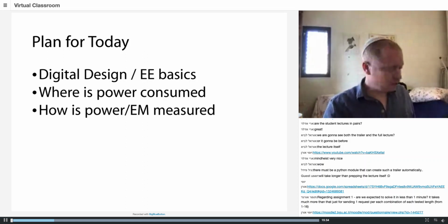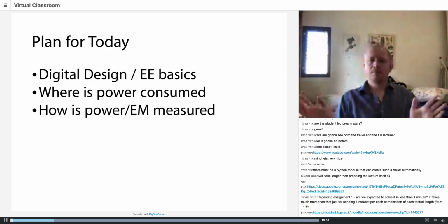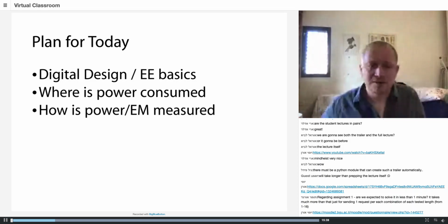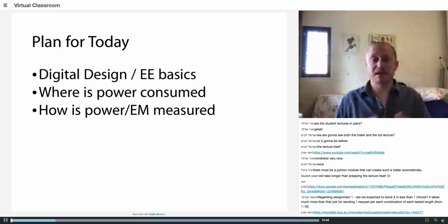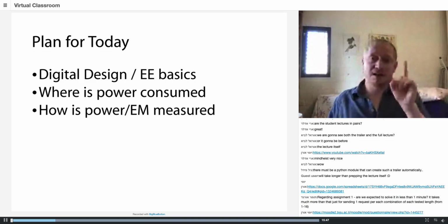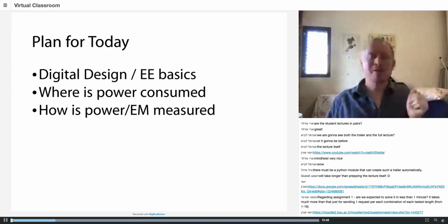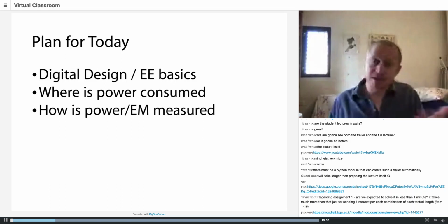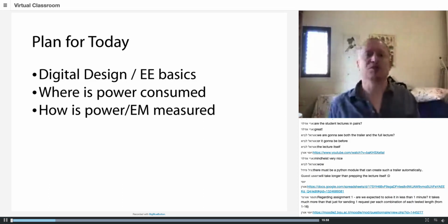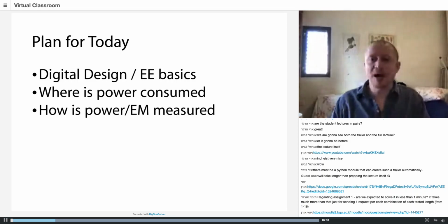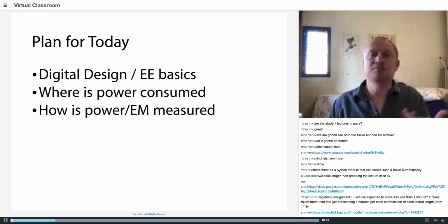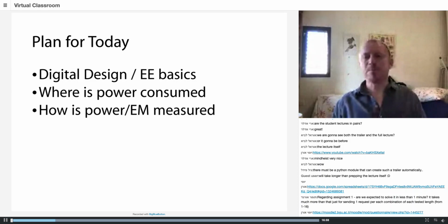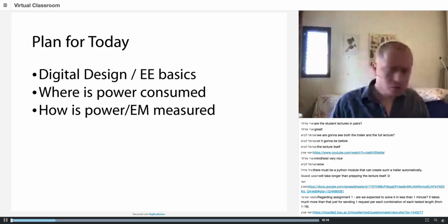So today I'm going to talk about getting you going on the path to performing power analysis. The idea is that previously the attacker had one kind of input, which is the timing, and this got us quite far, but you can do constant time countermeasures. Now we're going to talk about another kind of piece of information that the attacker can have, and this is the power consumption. So I'm going to talk about why devices consume power, how they consume power, and how you measure it. And this will take us through today.